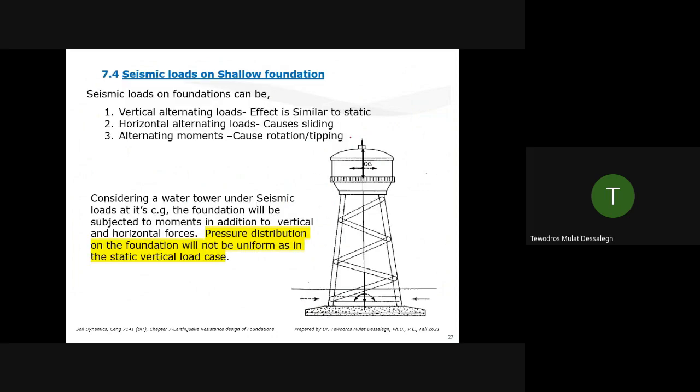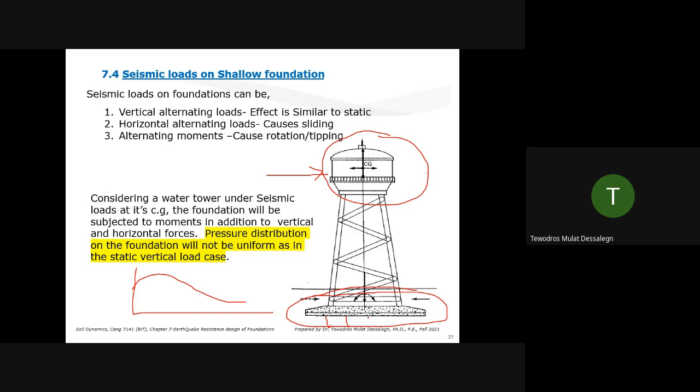Section 7.4, seismic loads on shallow foundations. It's complicated loading, right? You can have a vertical loading, like a water tank here. Last time we estimated the bending moment on a water tank using a response spectrum. I was trying to show you how you pick a response spectrum acceleration and use that to find forces at the top of the foundation. You can have a mat foundation or a pile and pile caps like that.